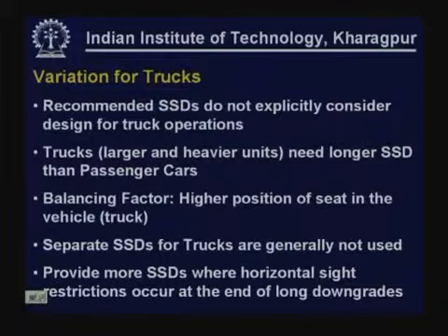Now, variation for trucks. The recommended design values for SSD are based on car traffic movement. They do not explicitly consider design for truck operations.